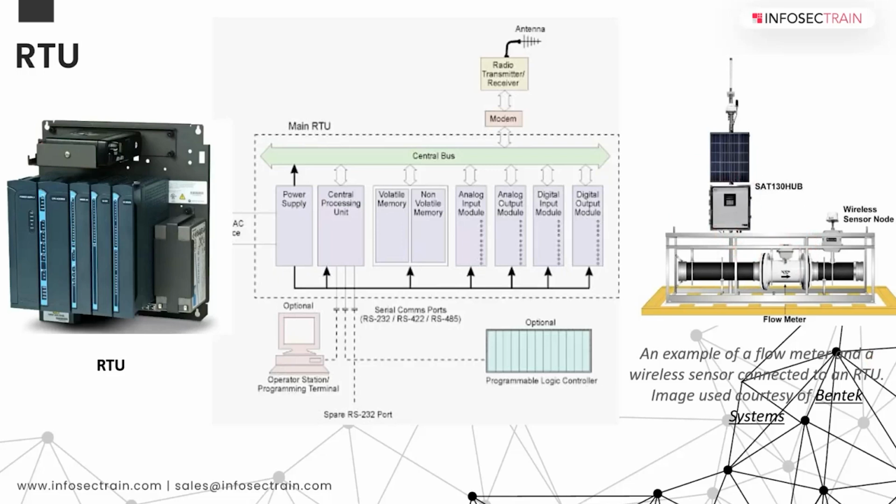That's what RTU is. The main purpose of an RTU is to monitor and control field devices and inputs like valves, actuators, sensors, and so on. RTUs are essential components of supervisory control and data acquisition, SCADA systems that we saw earlier, and these help to interface all the SCADA and the physical process by getting all the input data. This is RTU.